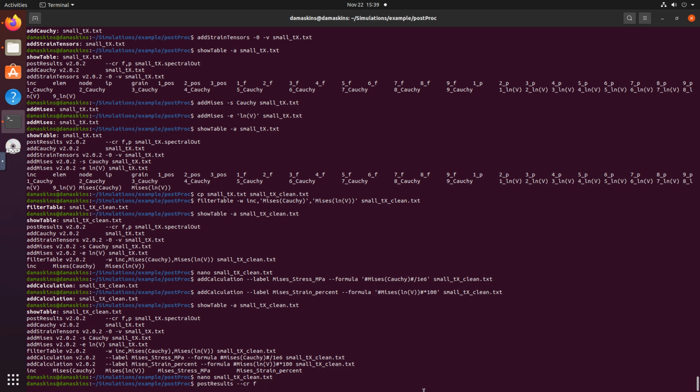So what we do is we say crystalline FP, and what else do we want to get out? Let's say phase, Euler angles, and texture. So all of this should already be exported. Otherwise, we will not be able to look into this.